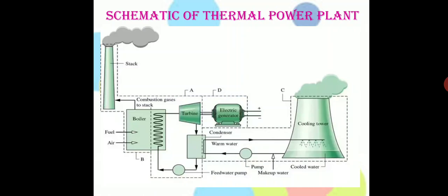This is done in the condenser using water in the cooling tower. The water in the cooling tower is circulated through the condenser. Heat energy in the steam is given to the water and the steam condenses back to water. The heat absorbed by the water is then released to the atmosphere through vapor and heated air through the cooling tower.